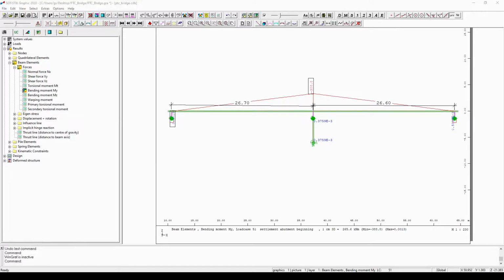I will try to demonstrate it by choosing the multiple dimension lines, and I will choose the single point object snap, and I will choose the node here, and then I have to once more choose the single point, F2, and then I need to select another nodal point, and right away if I hit enter and enter once more, then escape to terminate the command, what you will see is that I managed to measure the exact value of the first span with the help of this object snap.